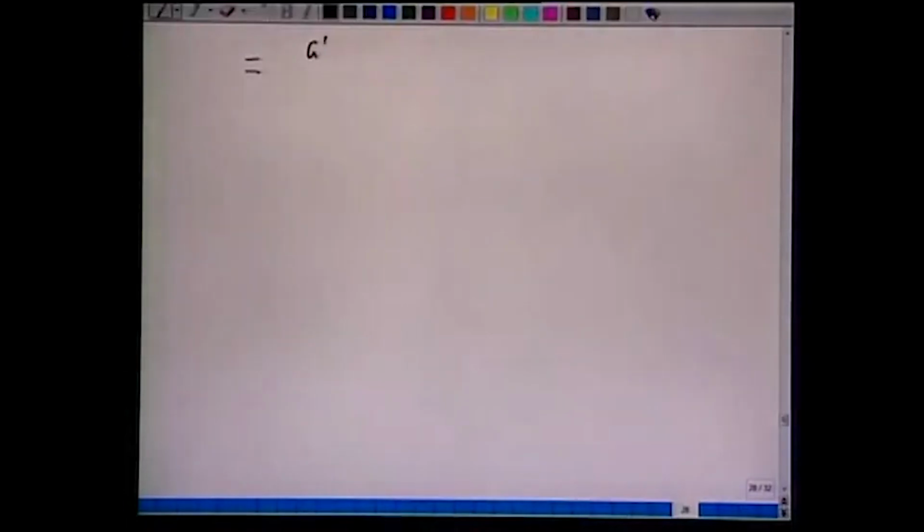So, this integral can be rewritten as G prime over k_y a times (1 minus y)_I m, into the integral from y2 to y1. Notice y1 is greater than y2. (1 minus y)_I m over (y minus y_I)(1 minus y) dy. Okay. So, we are talking of y and y_I.